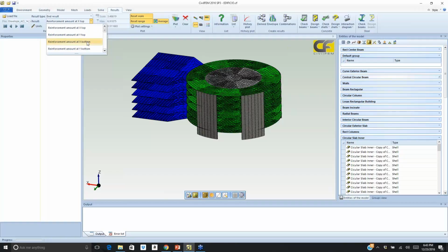Again, there will be reinforcement top and bottom because the seismic analysis will perform a vertical loading, not just downward, but also up. The results are, CivilFEM is very flexible in units. Normally, the results are represented as square inches of steel per linear foot of concrete matrix.